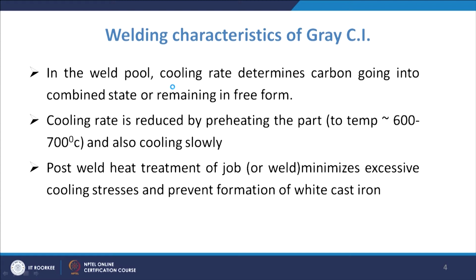That is the process followed while welding gray cast iron. We also do post weld heat treatment of the job, which will minimize the excessive cooling stresses and prevent the formation of white cast iron.